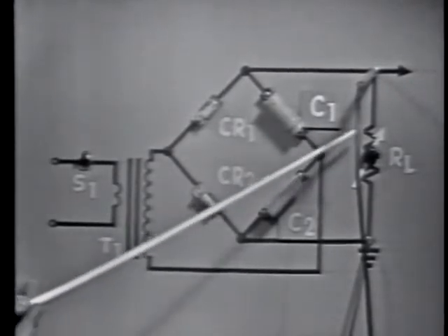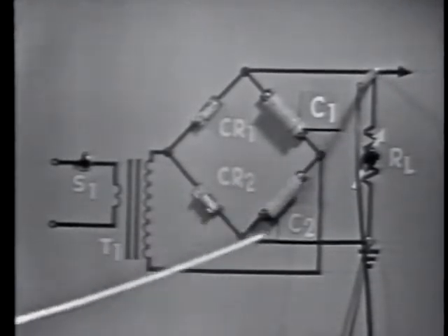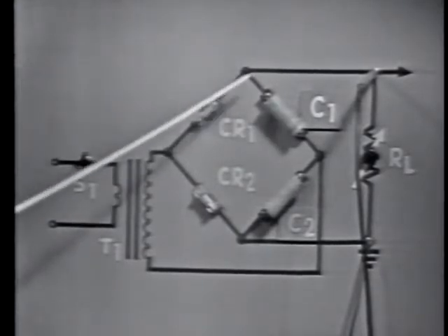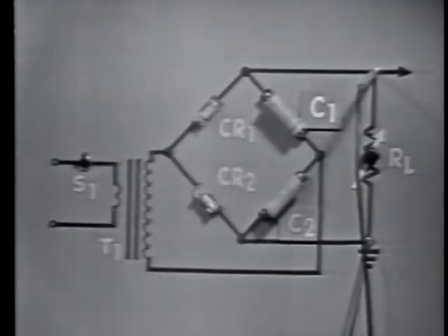If the load on the circuit increases, resistance decreases, and this decrease in resistance shortens the time for one time constant. This then allows the capacitors, that's C1 and C2 in this circuit, to discharge a greater amount between cycles of the input. So, average output voltage decreases.